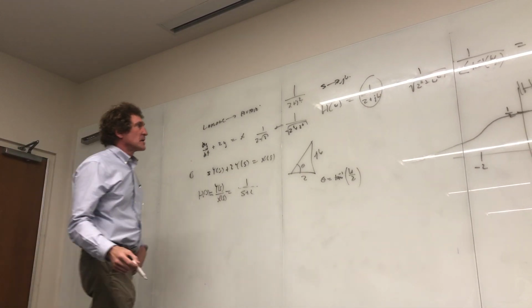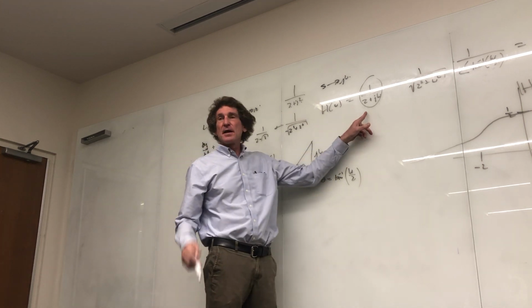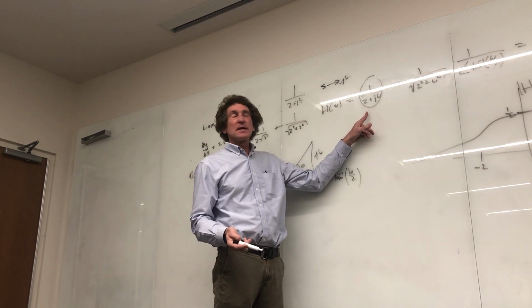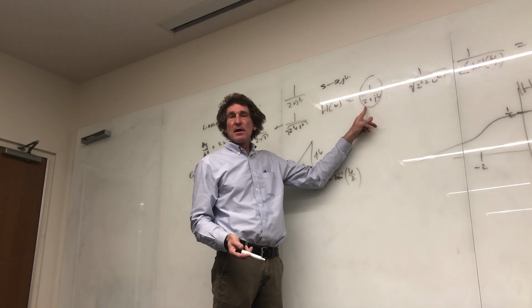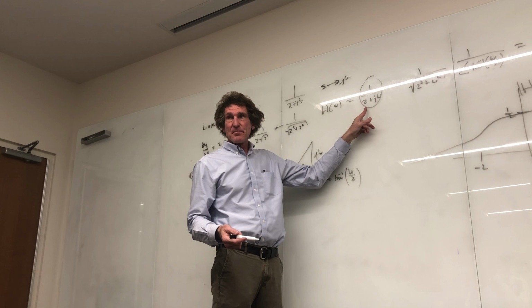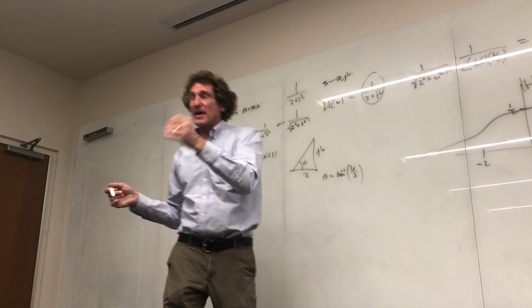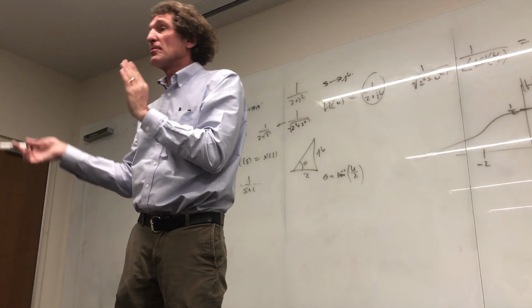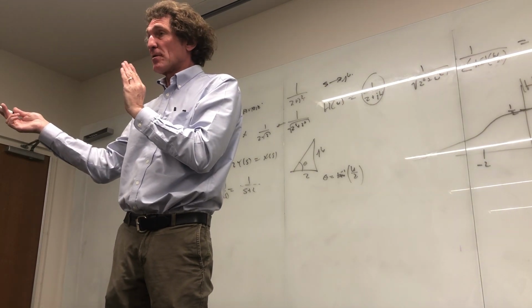What I do is just look at the function right here. If I have 1 over 2 plus j omega, what's the phase of this when omega is 0? Well, I have 1/2, don't I? What is the phase of a positive valued number? Well, it's just 0, right? If I have 1, it's at an angle of 0. That's an assumption because there's no imaginary component, correct, class?